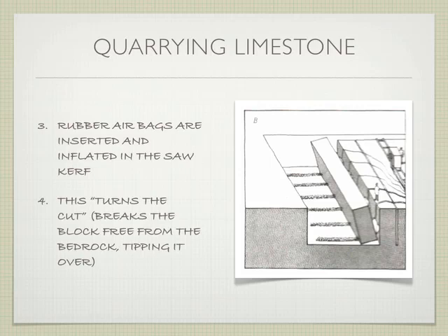Other options for this, if you didn't have the air pillows, you could simply drill holes, or use that saw cut, fill it with water, wait for it to freeze, if you have the ability to do that, and that would crack the stone. Sometimes if you're trying to do a foundation and you run across a big boulder that's underneath, like let's say you're up in Tahoe and you need to pour a foundation, you have a giant rock that's in the way, very common in Tahoe. You have to get rid of a piece of the rock. How are you going to do it? If it's the right time of year, you drill the holes, fill them with water, wait for it to freeze overnight, and suddenly you have a nice cracked piece that you can then remove.